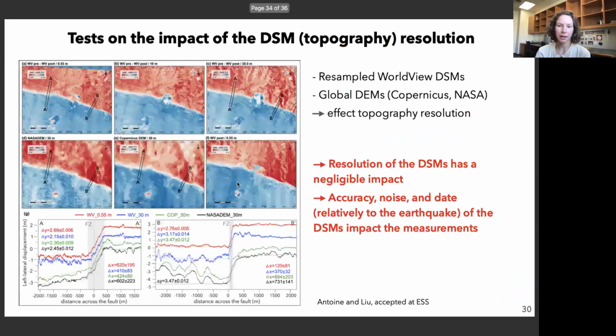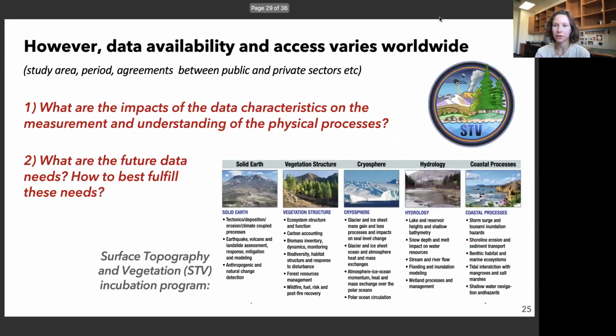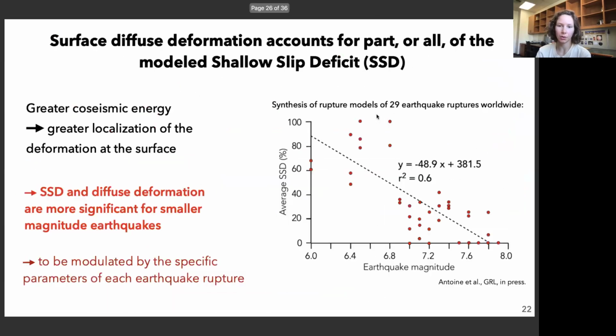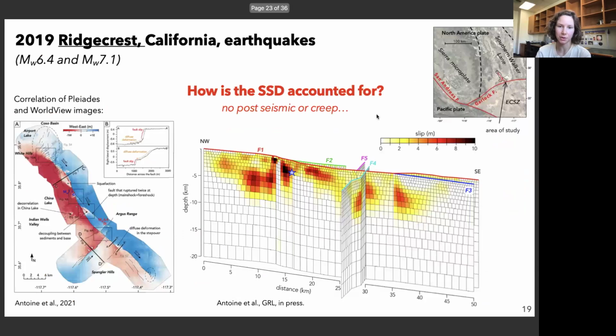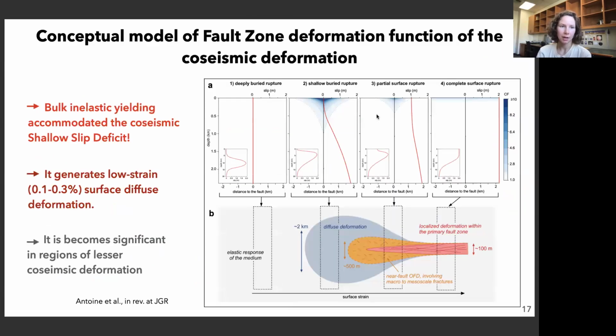Yeah, so it is related, and that's something that was really hard to understand all the mechanisms at the same time. So I didn't bring in that presentation the scaling laws, but this is what I've tried to mention here in this graph. The fact that if you have low surface strain, as we showed this 0.1, 0.3%, it is usually considered as elastic deformation.